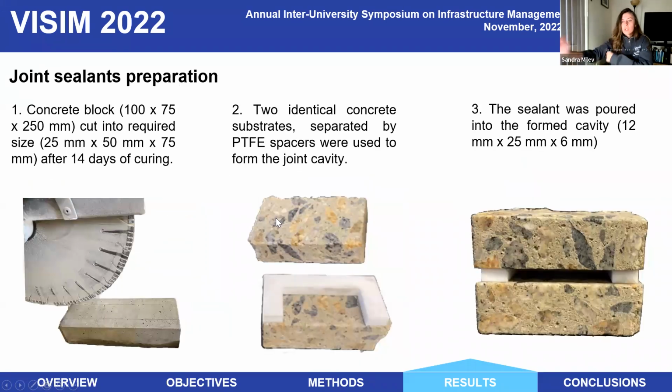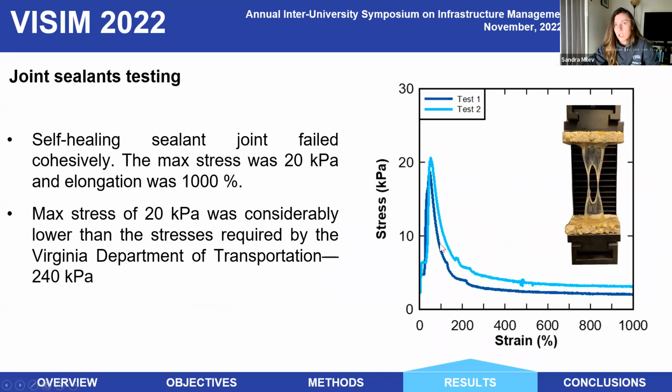For the adhesion test, we prepared the joint samples using 2 concrete substrates, and the cavity was formed by using this Teflon spacer, and then the sealant was poured inside the cavity and cured for 21 days, also in ambient conditions. These tests showed that the failure is cohesive,